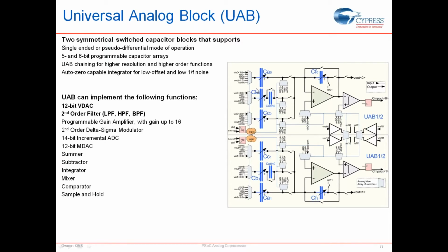Summer, a subtractor. So if you put inputs into each of these legs, into the different input capacitors, you could end up building either a summer or a subtractor based on what phase the inputs are being sampled at. Like I said, integrator.